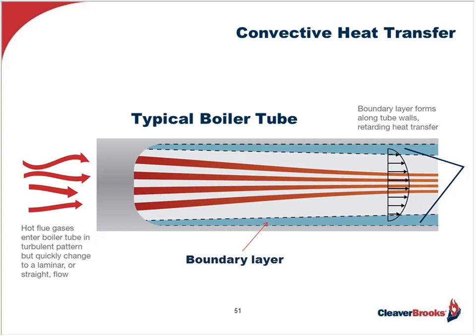Now, to counter this, designers include sufficient fan horsepower to maintain a minimum velocity, overcoming the delta P throughout the vessel, adding additional tubes or gas passes to allow more BTUs to be absorbed, thus increasing the heating surface, the size, and the weight of the boiler.